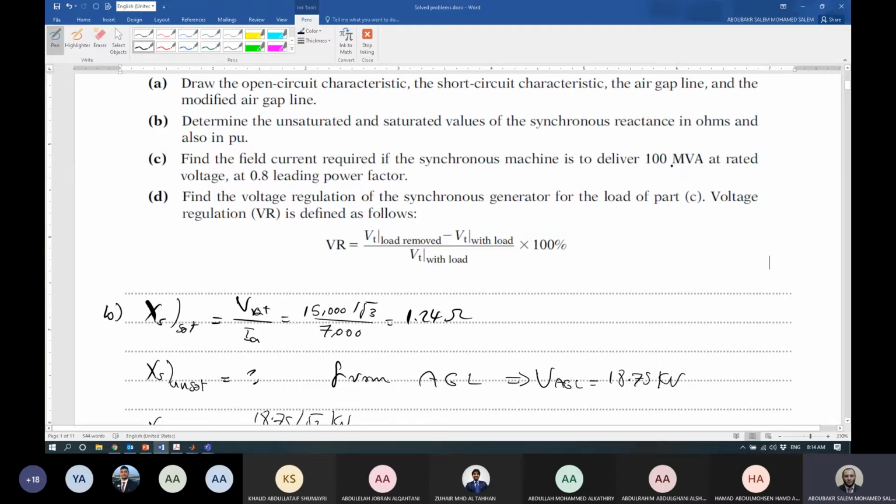So simply you have a loading condition now يا شباب. All the time, in order to calculate excitation voltage and the power angle, you have to find the loading condition. Loading condition means S with power factor, or P with power factor, or the current itself given. All of these can be used to get the current.